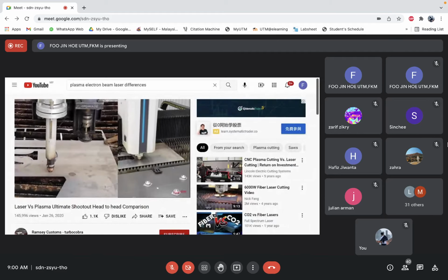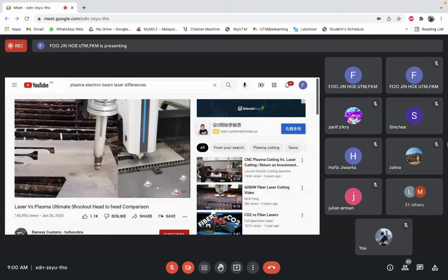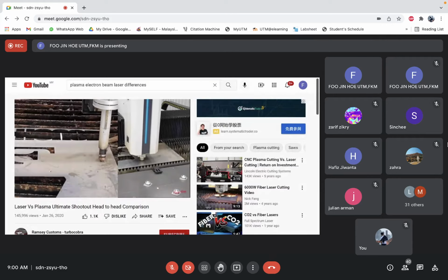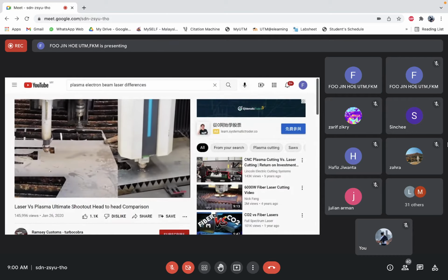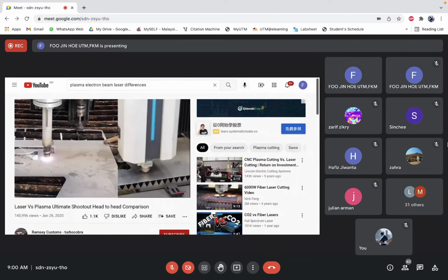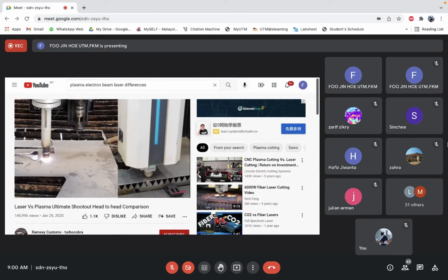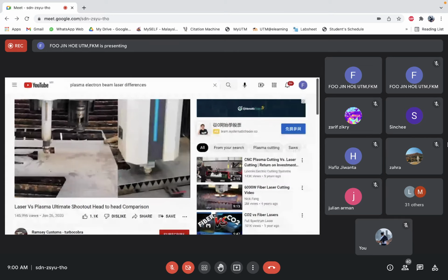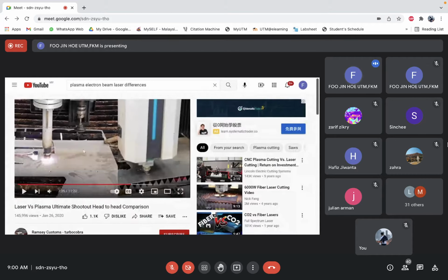All right, guys, check this out. I'm going to do a little voiceover here real quick while these are cutting. I wanted to point out that the lift height on both the laser and the plasma is set to 2 inches. But if you notice on the laser, the short moves between each of those holes, the main difference is the retracts and rapids.